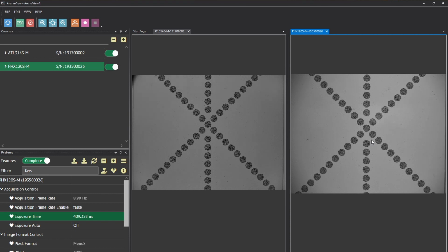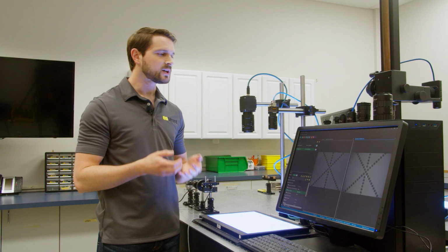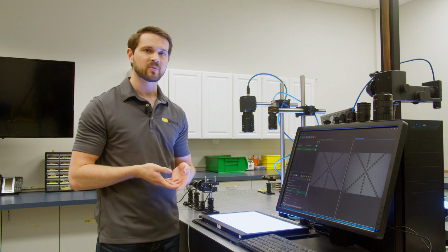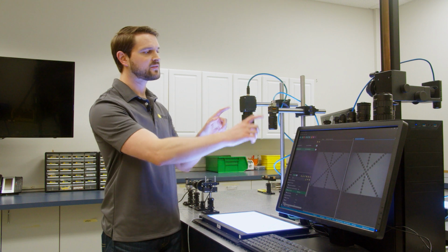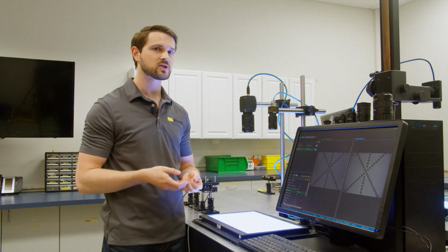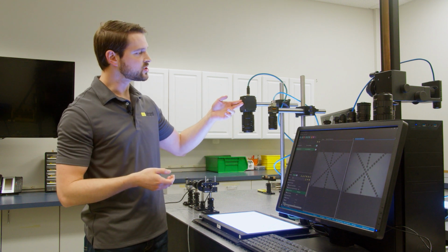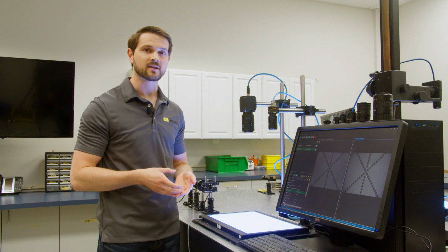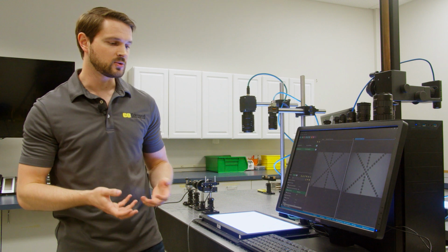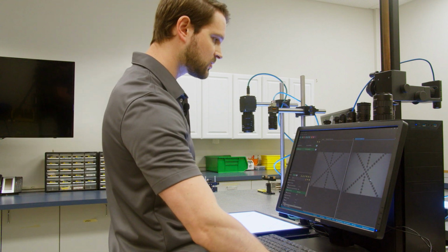In this particular case, we're looking at this 4-inch, about 100 millimeter horizontal object. These are star targets. I want to take a look at what actually happens now that we have different megapixel counts. Because we have the same field of view but different sensor sizes, our magnifications are actually different. The magnification on the 32 megapixel system is higher. How does that correspond to a different image? Well, let's take a look at this. Let's zoom in on some of these.